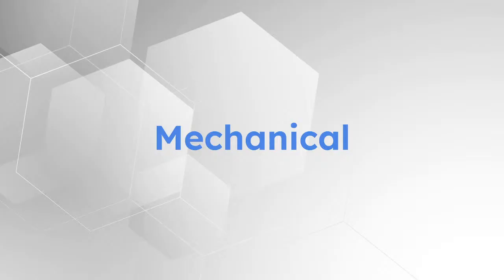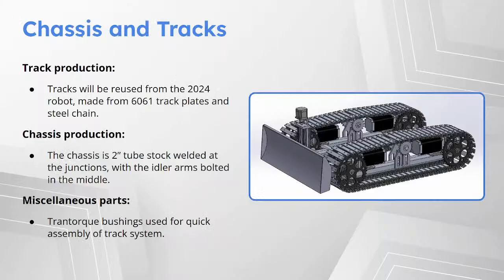Good morning. So now we'll go into the mechanical section. Chassis and tracks. If you saw our project last year, this is pretty similar with a few key changes. First of all, we have shortened the tracks by about 10 inches, and we have lightened the sprockets by removing much of the hub and surface material. And this year, instead of using a bucket wheel like we did last year, we're using basically a bulldozer. So tracks are reused. They're the same material, steel chain, 6061 aluminum grousers. Chassis constructed the same way as well, 2-inch aluminum tube stock, just welded together, simple, strong, effective.